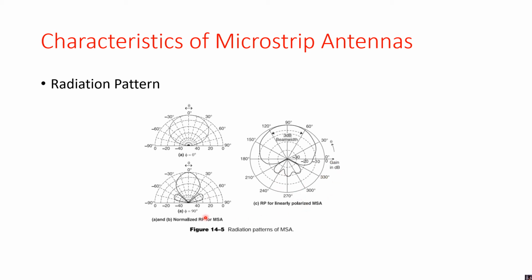This figure shows a cross section in the horizontal or the azimuthal plane. Here the scale is logarithmic and the power radiated at 180 degrees is about 15 dB less than the power in the center of the beam at 90 degrees. The beam width is about 65 degrees and the gain is about 9 dBi. An infinitely large ground plane will prevent any back radiation, but the real antenna will have a fairly small ground plane. Also the power in the backward direction is about 20 dB down from that in the main beam.